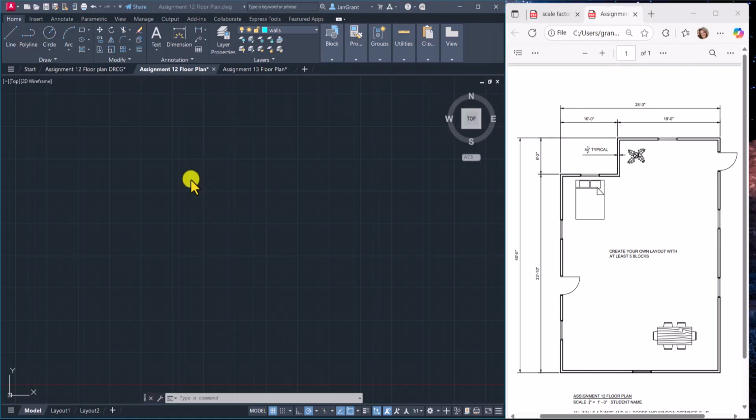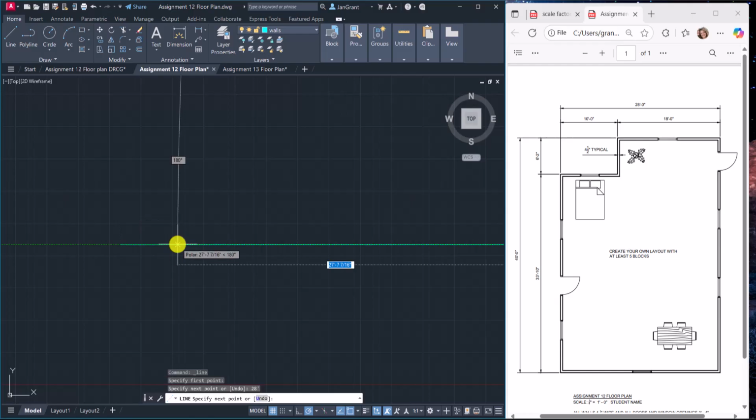So let's do that first. Let's draw a line that's 28 feet and see how far over it goes, right? So just instead of using the polyline just yet, let's start the line command. We've got the walls layer current. I'm going to click a point and pull my mouse. Now, don't forget the apostrophe. Type in 28 apostrophe. It's that keyboard button right next to the enter key, apostrophe, enter. And then enter again. And what you'll see is that the line goes way off the board.